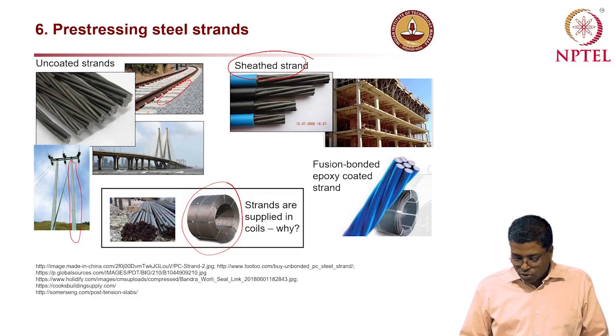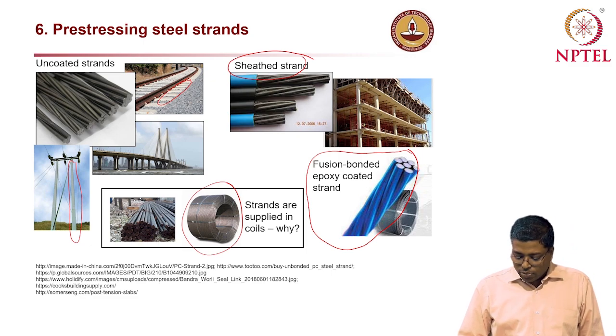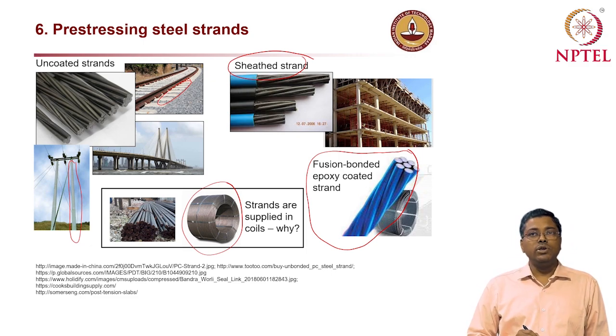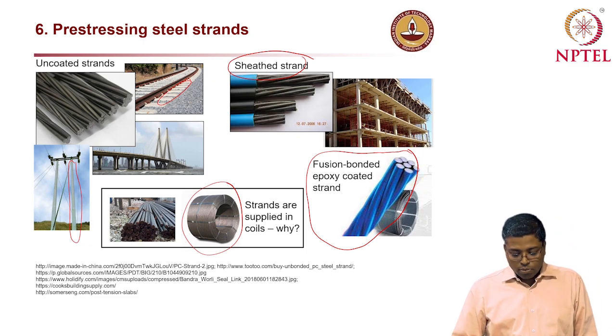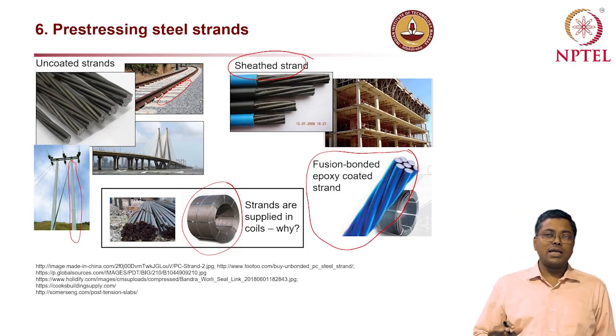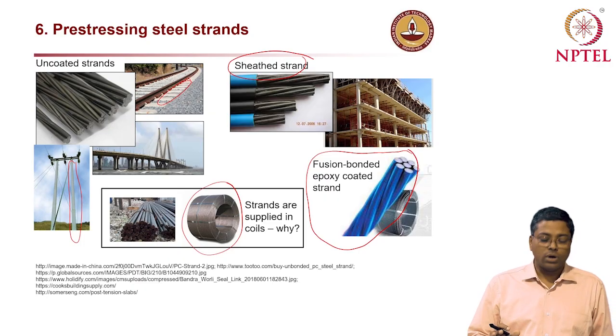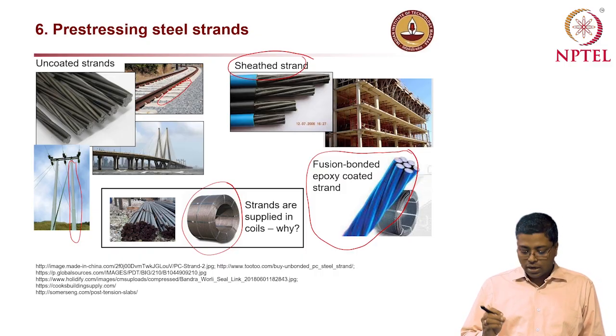And now in some new projects, we have even started using fusion bonded epoxy coated strand. I would say we should be very careful when we use epoxy coated strand. More details I'll cover in the next lecture, but there should not be any scratch on this epoxy coating, and it should not be exposed to ultraviolet radiation or sunlight.